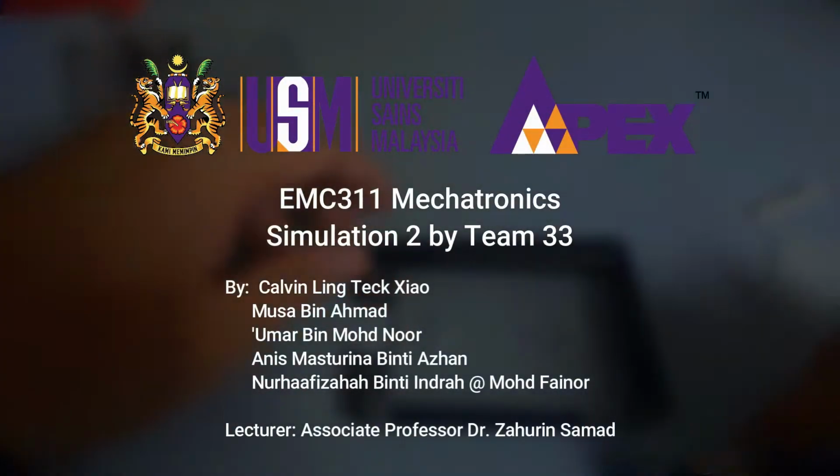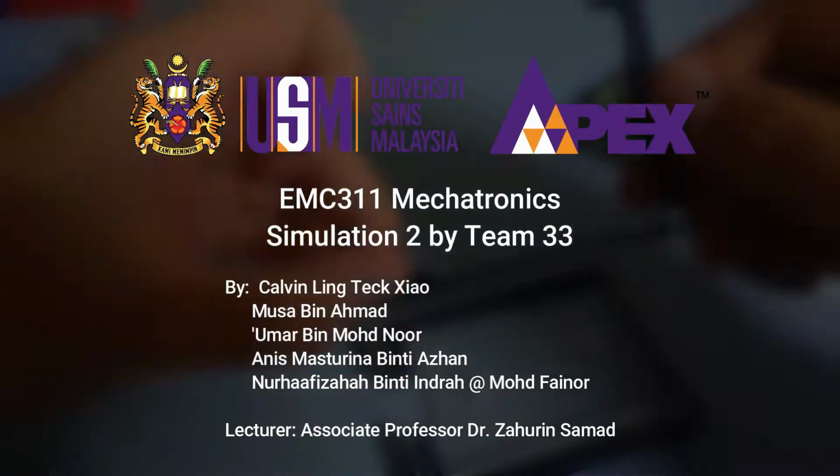Welcome to the second Raspberry Pi simulation focusing on GPIO. This time we will be playing with Python and Node to operate components such as LEDs and BME280 sensor. You need to have these components as well as the software installed on the Pi before proceeding. But just a heads up, never run any code when disconnecting the jumper wires on the Pi or it might cause short circuit. Now set up your Pi with the peripherals as seen here and switch it on.